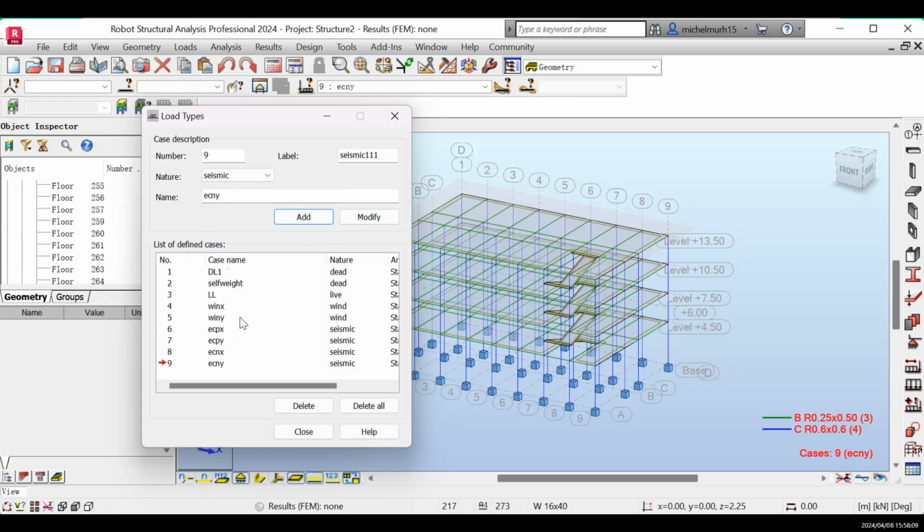Here you can see that some people are going to ask me about the staircases. The staircases can be temporary, or they can be attached. Some people use staircases that can be moved, and some people just attach their staircases, right? My staircase is going to be under the dead loads, so they are going to impact the overall forces of the building. So I'm going to use them in dead loads. This is the whole idea about the video.